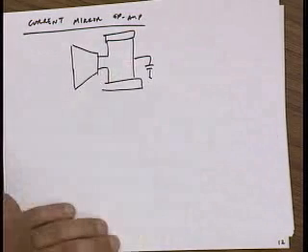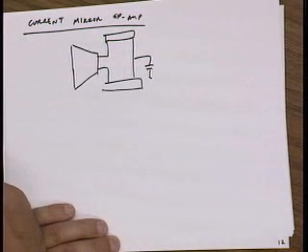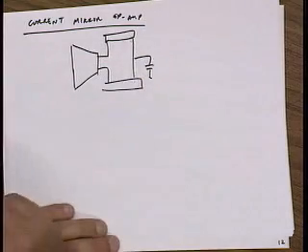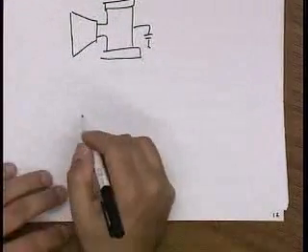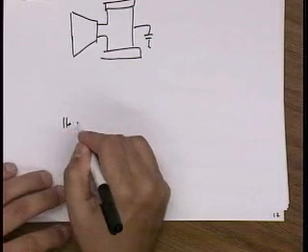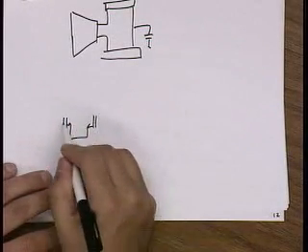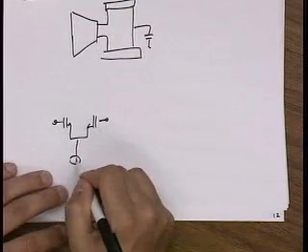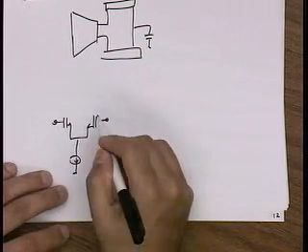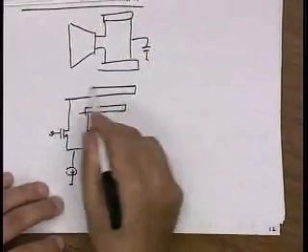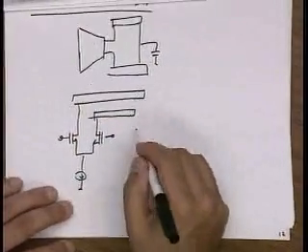Let's say in a single-ended version of the output, or in a fully differential version, this would be the plus side, this would be the minus side. And so I can use, again, a traditional input stage. This is not class AB, so it will have slew rate limitations. But it's actually going to be better, and we'll see why.